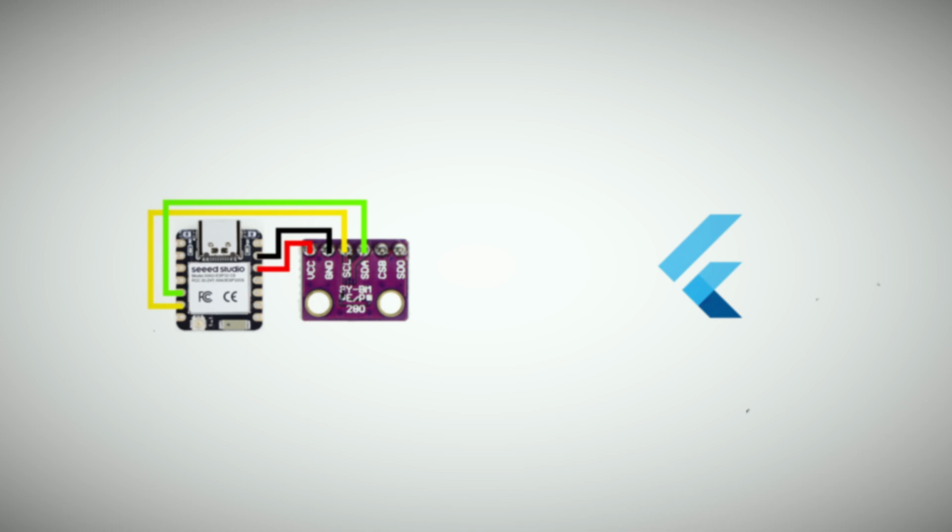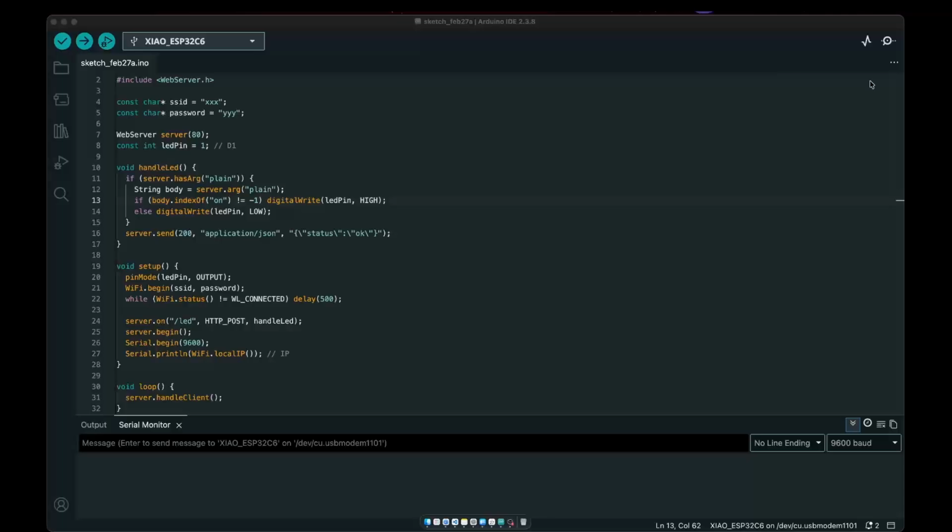The principle is simple. Our Flutter app acts as a client that sends an HTTP POST request over the local Wi-Fi network. On the ESP32, we will run a mini web server that receives this request, extracts the data in JSON format, and changes the state of the GPIO pin connected to our LED accordingly. We will start with the ESP32.